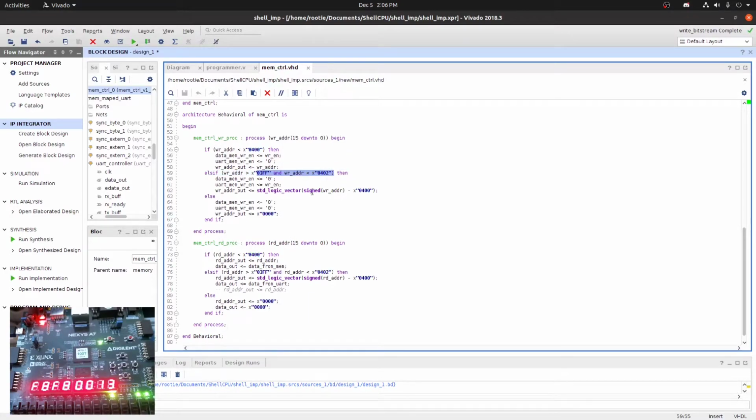between these two addresses, I don't want that block RAM and the UART controller to have to think about translating the address from 400 to 0, since whatever logic Vivado decides to instantiate to decode that block RAM is not going to be accounting for a 400 in the address. It's going to be a 0 or a 1 since it's a small block RAM. So I take that address and subtract where it is from the software perspective, and if the CPU wanted to address 400, the UART controller ends up getting address 0.